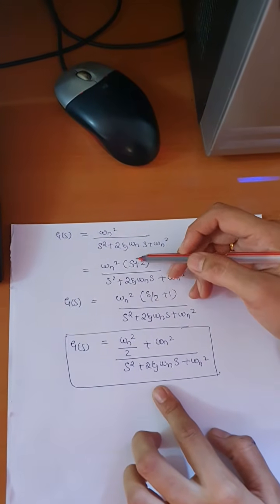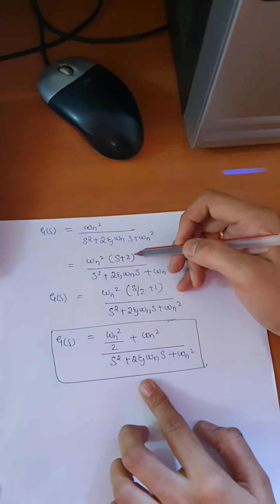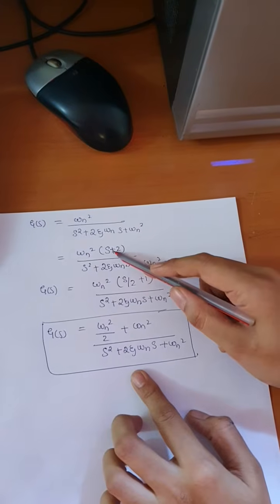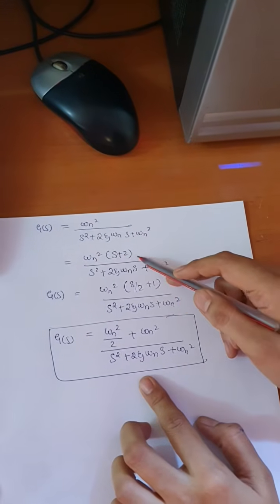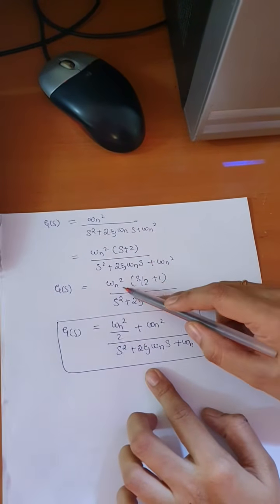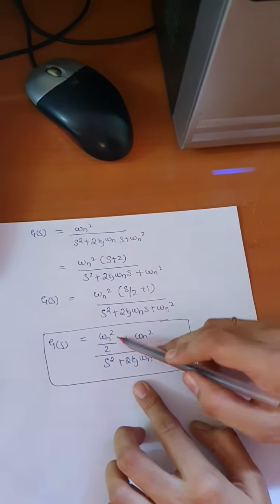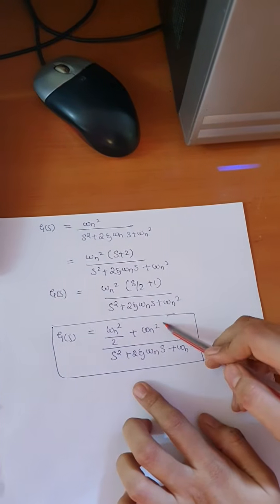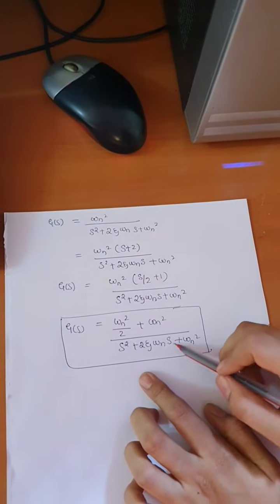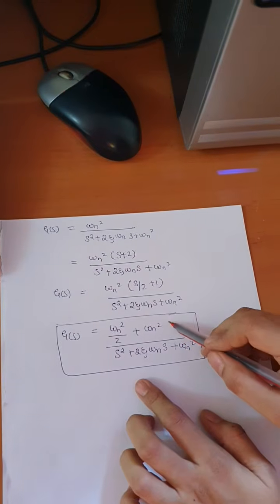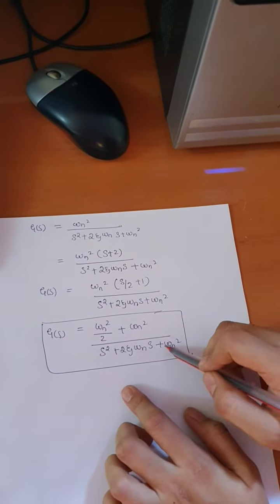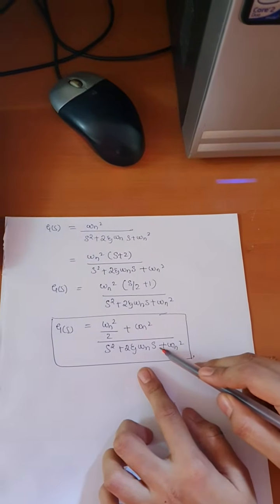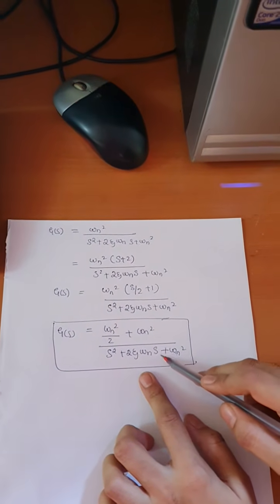Omega n square is multiplied as s plus z. Again, instead of writing s plus z in the numerator, I will write this as s by z plus 1. So after writing it this way, multiplying omega n square with these two terms, we obtain omega n square by z plus omega n square, divided by the denominator, which will be the same as it is, because we added only the zeros in the numerator. You need to remember this transfer function, because this is our new transfer function after the addition of zeros.